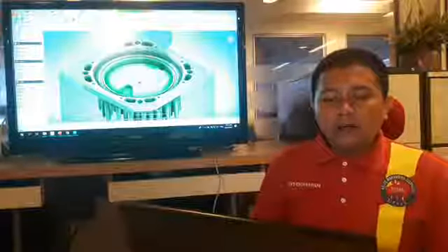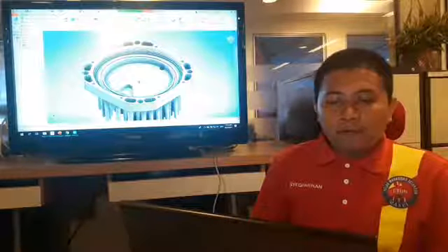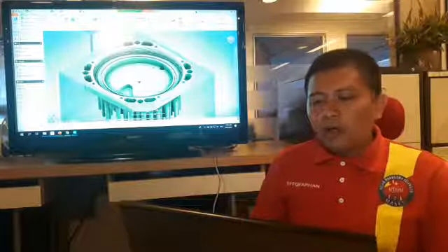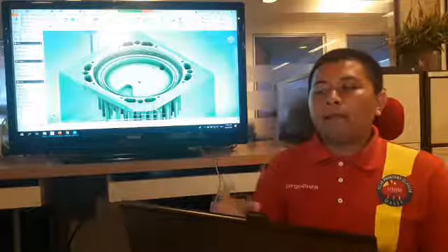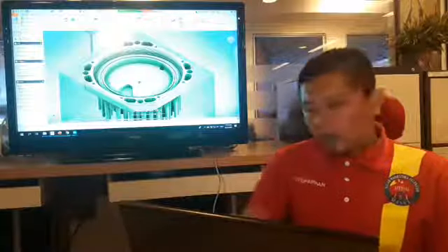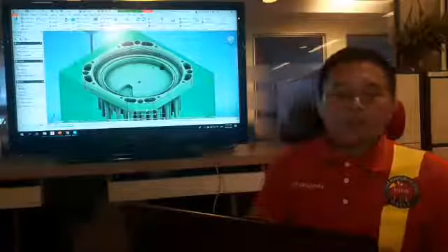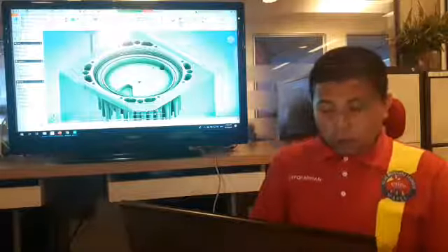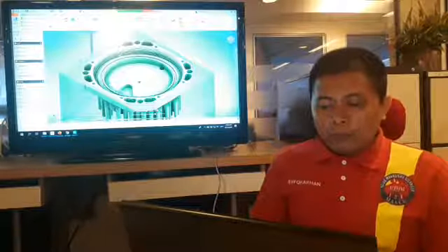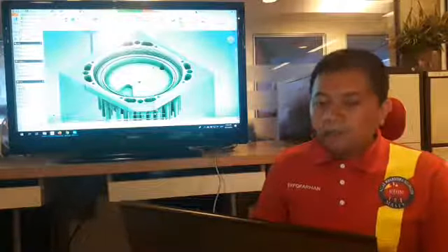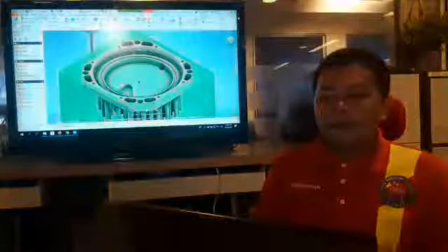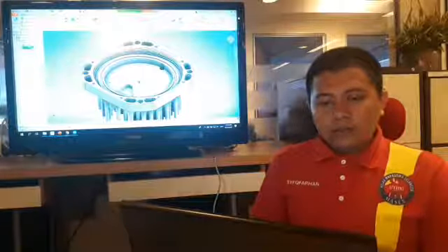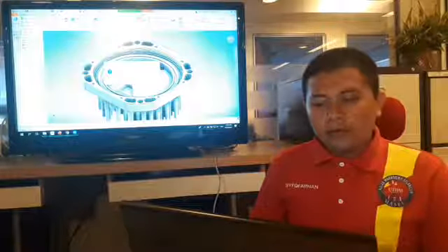Okay, for this case, you can try to do the full setup simulation. If you face the same issue, that means you need to make a special tool to do the face cutting over here. Or you can just simply do the drilling first, and you simply do the face after that. After that the drilling. Okay. Right. So I just simply delete this.